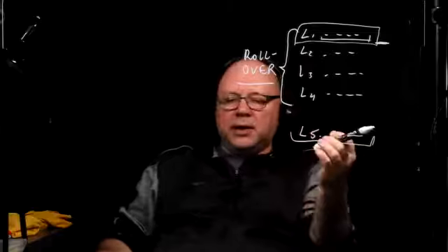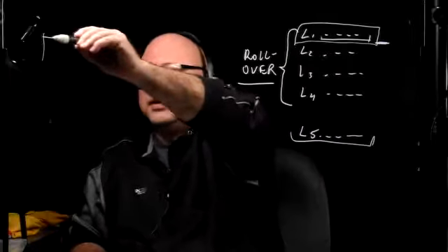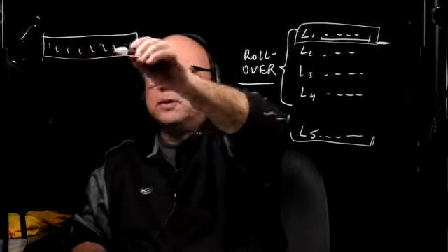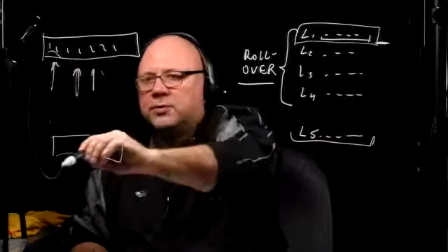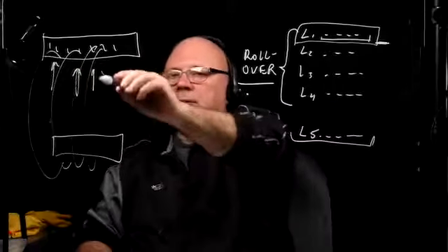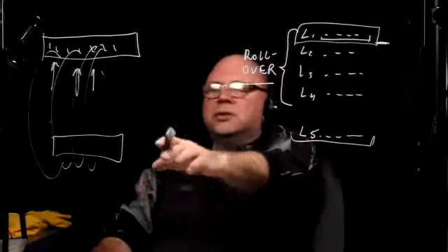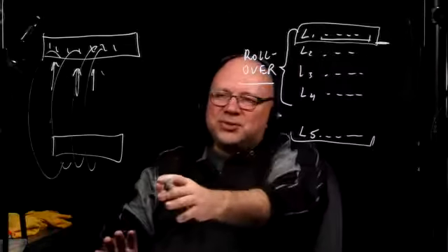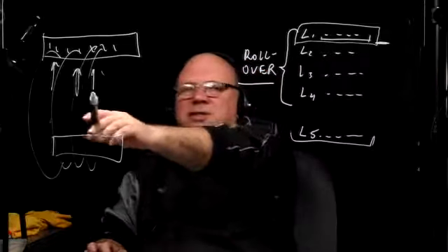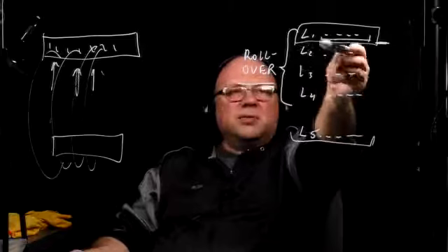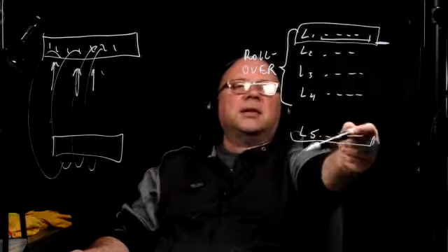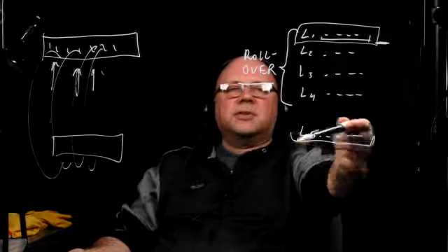For that purpose, sometimes when somebody connects those lines, because those lines are going to be terminated on a termination strip, right? Those lines are going to be terminated, and they are going to be cross-connected to another termination strip that is connected to the telephone system. And sometimes by mistake somebody connects something else, so the telephone system would have connected lines 1, 2, 3, and 5, and then line number 4 will be connected to the fax machine.